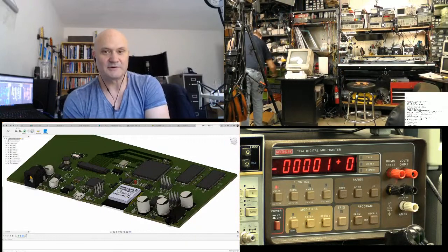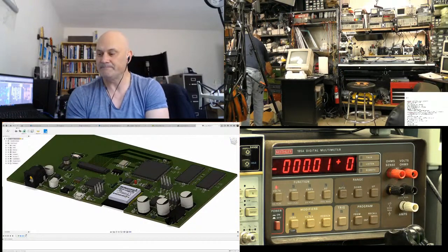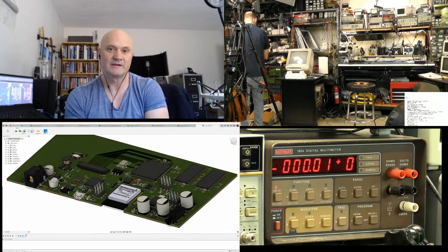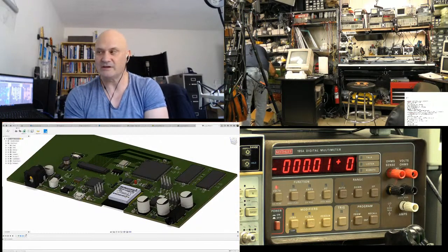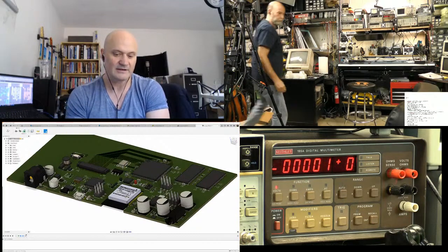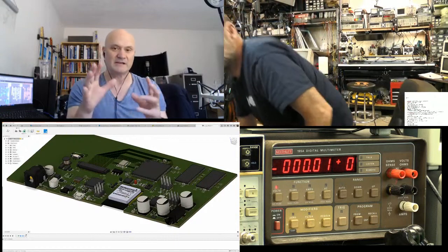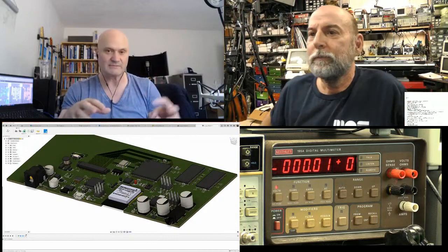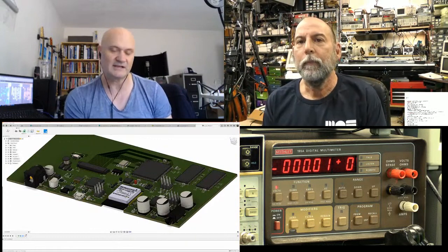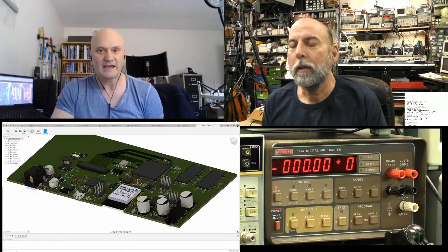They still have a lot of logic space on them. And if you don't need DSP, if you don't do multiply accumulators, if you're just doing a whole lot of muxing and configuring and doing state machines, things like gates, if you just need gates and state machines, they're perfect. And that's how they're marketed.